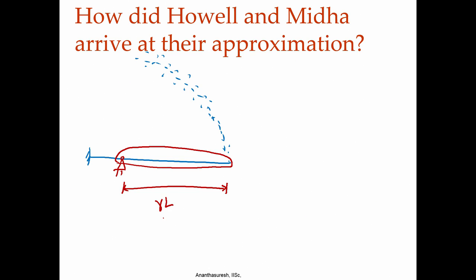They try to find this gamma through fitting in such a way that the angle, if this were to go like this, from here to here, they try to maximize this angle. To what extent can I go in terms of rotating this crank, in other words bending this elastic beam, so that the error between the circular arc and the spread of data is minimized.